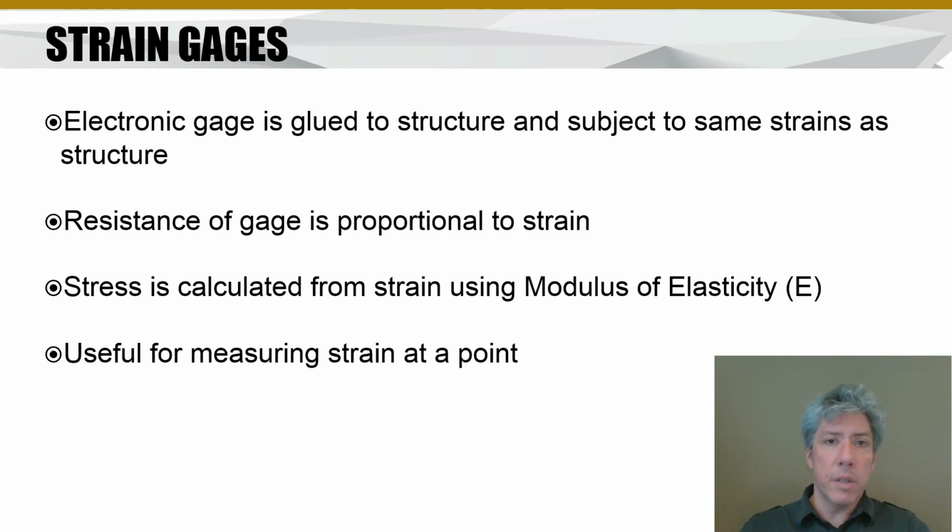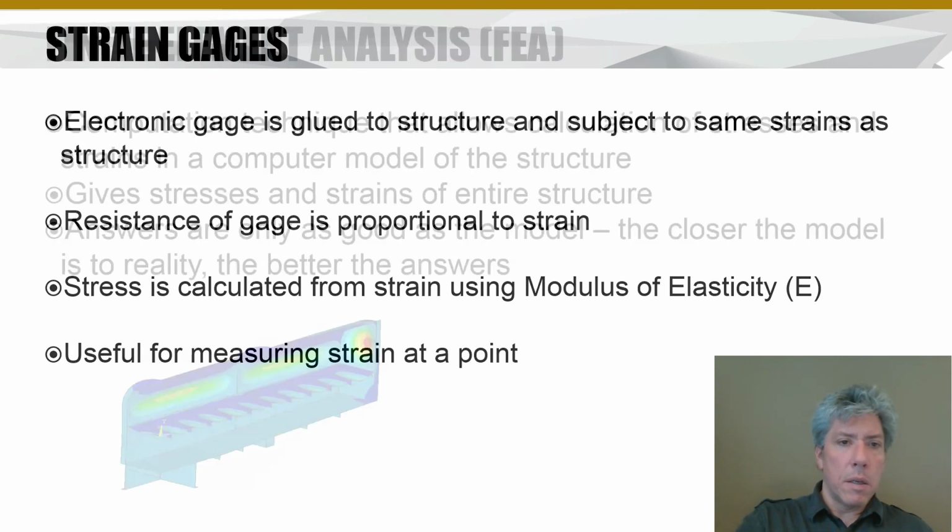Through Young's modulus then, since stress and strain are linearly related, at least if you're not loading the material too much, you can figure out what the stress is. Now if you get outside of the region where the stress and strain are linearly related, well then all bets are off on your stress-strain relationship. Okay. That's it for that one.